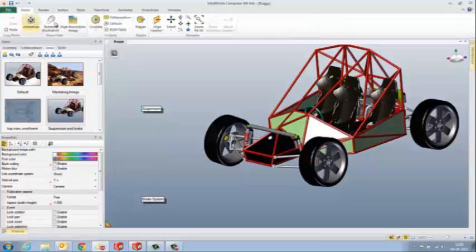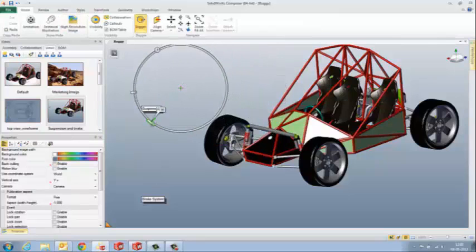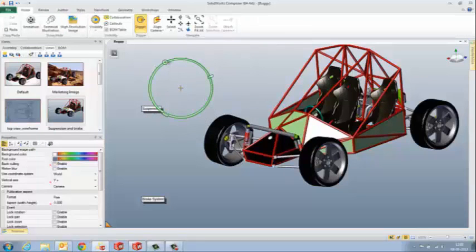Here what we can do is we can just go to Digger. I have something called the Digger tool, wherein it helps me to create the detailed views very fast and very accurately. Now I just click on this spanner icon, I'll get the options that can be used, and now this plus button is to change the center of interest, that is the area of interest I'm looking at. I just place it near the suspension system, and what I can see here is onion skin.